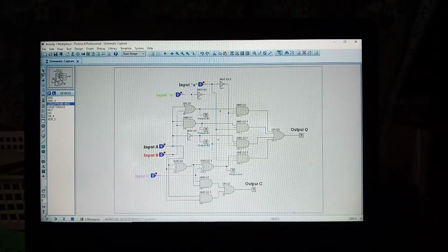Let's run the simulation. Everything is accounted for, no errors. As we can see, the NOT gate sends the opposite. Now let's look at the first three gates, the OR gate, the AND gate, and the NOT gate. When we indicate a 1, for the OR, it's always 1. For the AND, because there's a 0, it will always be 0. Because input A is connected to the NOT gate, it will always be the opposite of the input, so 0. As you can see, that is functioning.